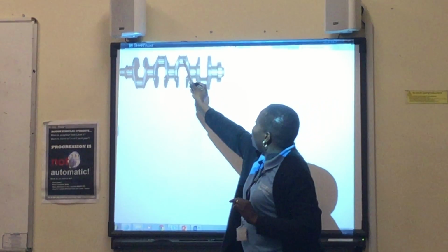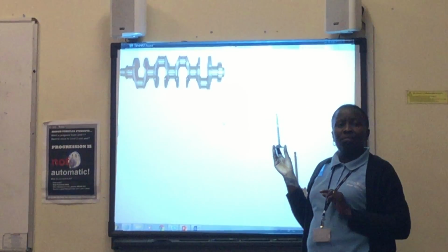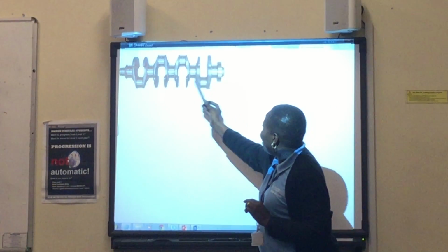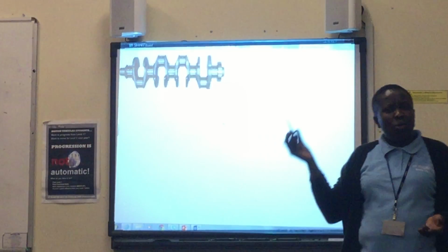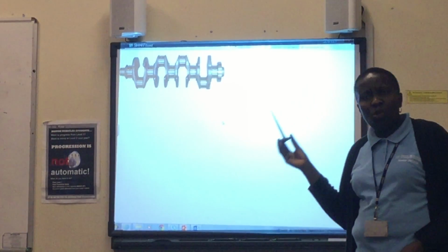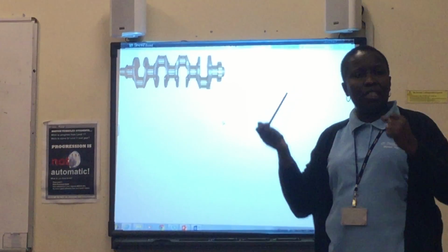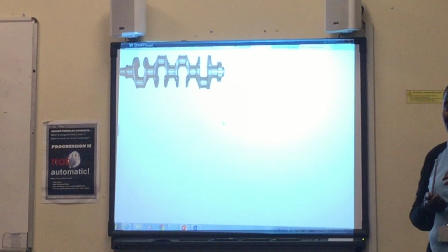At that position, are 2 and 3 at TDC or BDC? TDC. Then 4 and 1 are at BDC. So it is the setup of those journals which makes 1 and 4 married, and 2 and 3 married. Are we clear there?